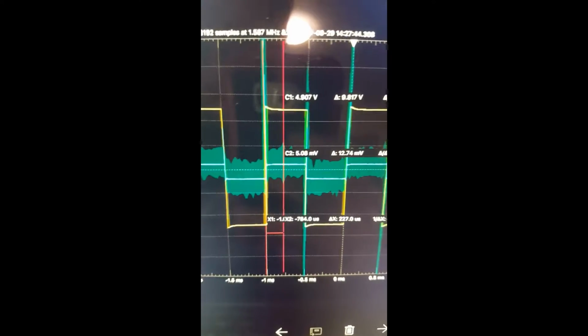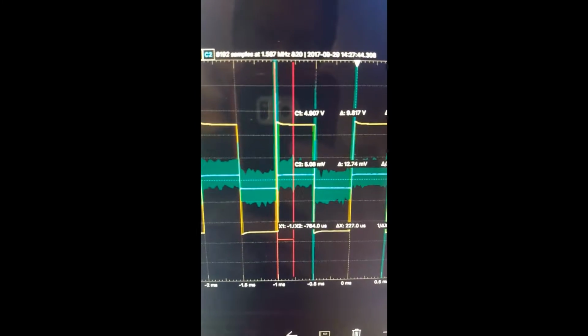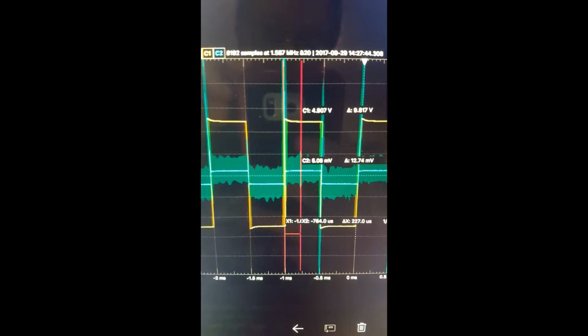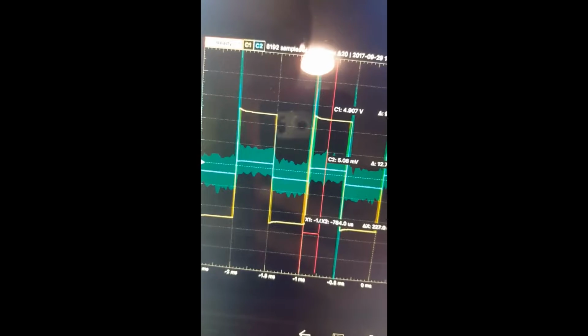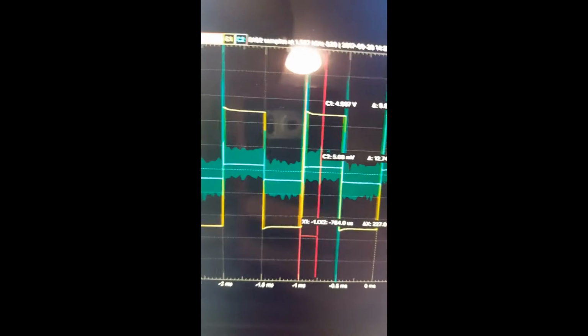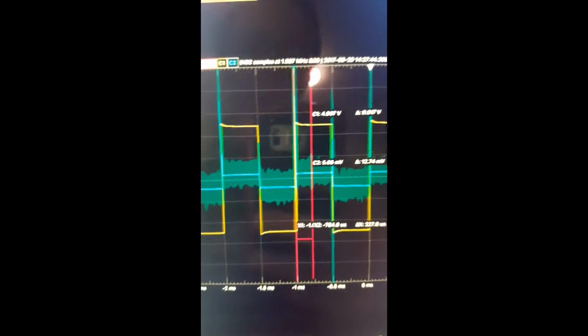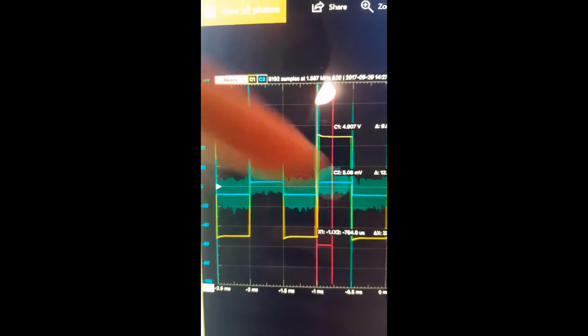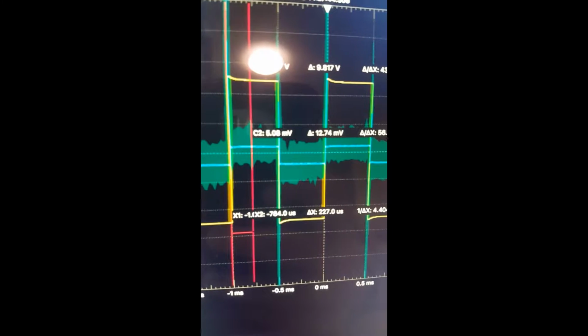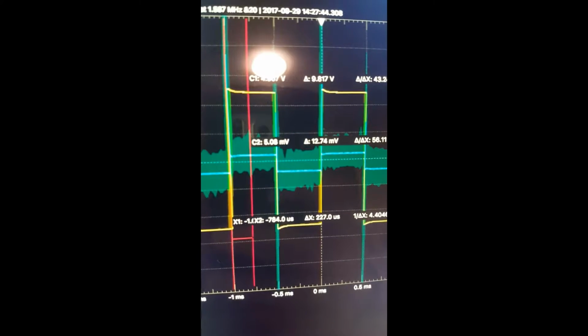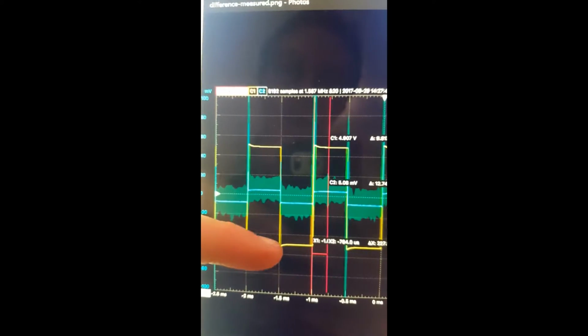Here's the differential amplifier output, where the blue is the output signal and the yellow is the input circuit. You can see that the blue signal is very noisy, but we took the average of 20 samples, and that made it less noisy. And then we took measurements at the high points of each of the signals, which allowed us to again calculate the slew and also the common mode gain by taking the peak-to-peak voltage.